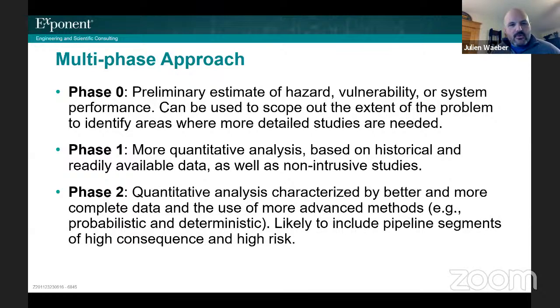You can take that one step further then and do a more qualitative analysis, implementing these geohazards frameworks, as I'll discuss in a minute. And that'll often be based on historical and readily available data. You can do this without any site investigation, really, for many areas, especially in the United States, where the USGS and local agencies have done a significant amount of work that we can base ourselves off of. This information is readily available to everyone. And so you can do this in a non-intrusive way and get a firsthand sense of the risk to the system that you're interested in looking at.